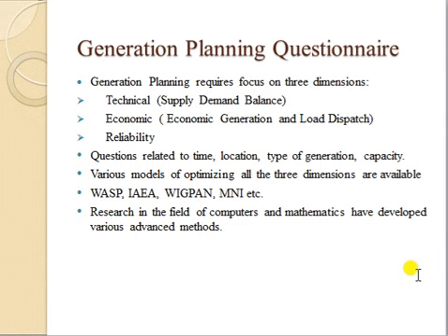Now these two things, the sequence may be changed, because sometimes coal is available, so you are putting up a power plant, and sometimes you are deciding first what the fuel may be, then you check the availability of that fuel, and then you decide the location. So depending on whether you are going to fix the location first or the fuel first, that may vary. And then again, what's going to be the capacity? In thermal power plants in India, you are aware there are technologies like 500 megawatt, 660 megawatt, 800 megawatt. So which capacity you want to expand, that decision is also to be taken.